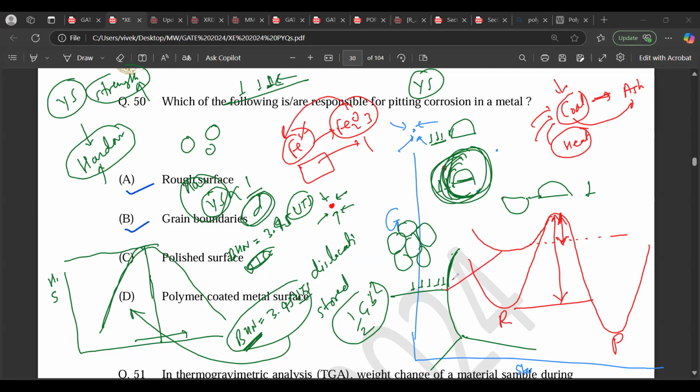So it has to jump from this grain to this one, and to jump across the grain boundary you have to give extra energy, extra strength, and that is how the strength is increased. Every grain boundary acts as an obstruction. We call it grain boundary hardening. So fundamentally, what we are doing is stopping the dislocation.